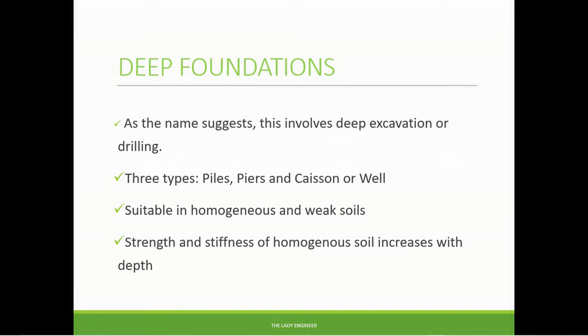So we use this type of foundation for weak soils or homogeneous soils because it is a well-known fact that the strength and stiffness of homogeneous soil increases with depth. Remember, we want our foundation to be suitable, that's why we are looking for a stable strata on which to lay our foundation.